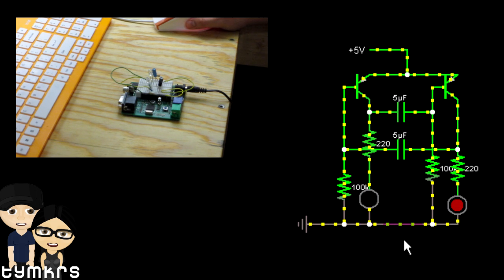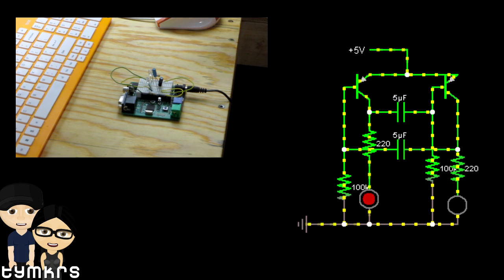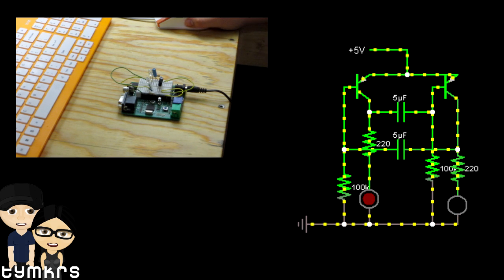So depending on how you change these capacitor values, these LEDs might be on for longer periods of time, or shorter periods of time. You might see more fade. I think if the capacitors are too small, then you'll end up seeing way too much flicker. And now I actually have a real version of it to show.